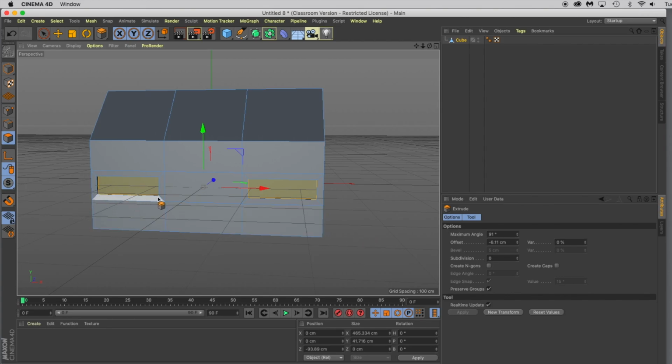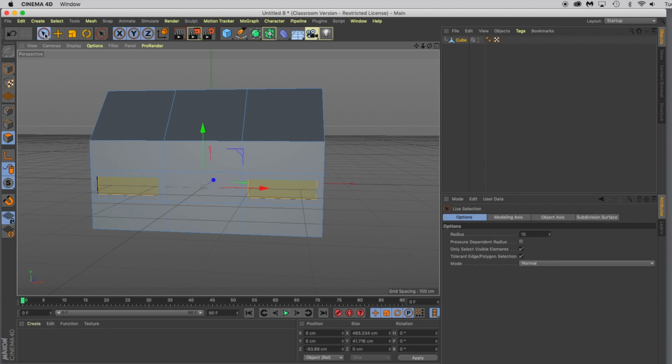And these little features in the 3D print model will just make it look a little bit more authentic. Now we need to select the framing around the windows, so we're going to go up to our selection tool here. And instead of trying to hover around and zoom in and try to be crazy exact with the selection tool, we need to bump this radius down a little bit. The default was 10. I'm going to go down to about 3. And now I can make smaller selections, and holding Shift on my keyboard I can just very quickly go around and click on the geometry that I want to adjust with these window frames.